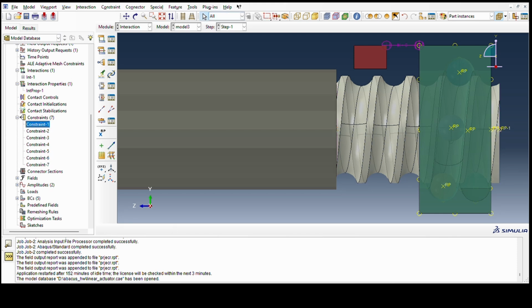Each ball is made as a rigid body using the rigid body constraints, and I made this block a rigid body as well to reduce the computation complexity. If it is a deformable object, the computation cost is higher. Then the housing is attached to the slab using a spring and damper system.